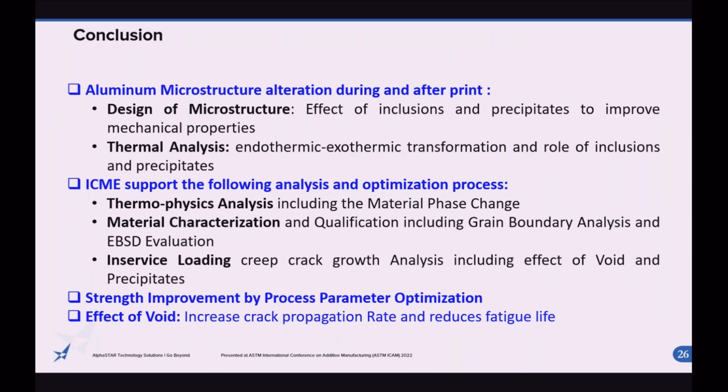So in conclusion, the toolset, with the understanding of the thermophysics, the incorporation of the build plan and the macro behavior based on print path coverage and print error management, and then taking all that information and mapping it into material modeling, feeding that into thermostructural analysis, we're able to not only understand the impact of, say, thermal analysis, endothermic effects, exothermic effects, triggering of inclusion or the impact of inclusion, so the triggering of precipitates, and how that ultimately impacts microstructure.